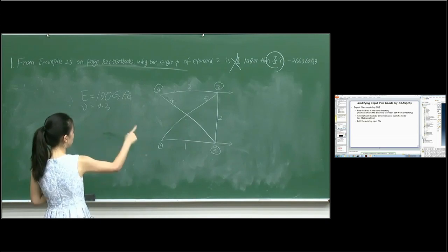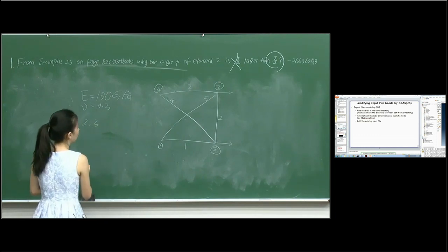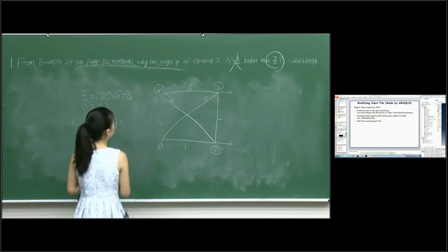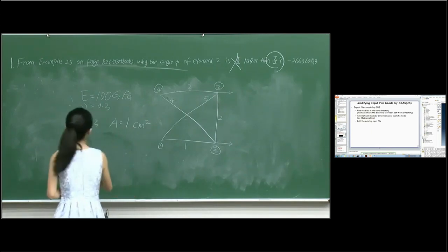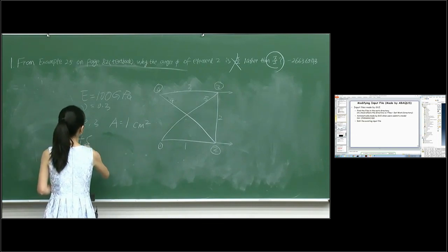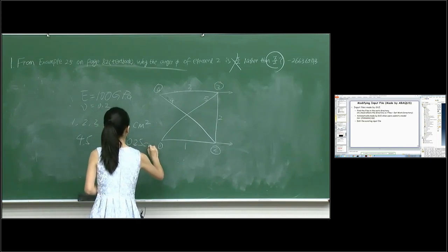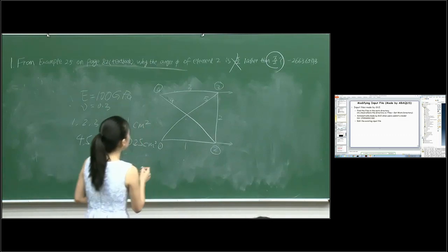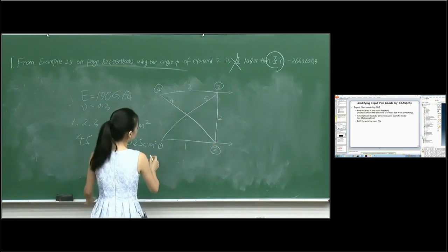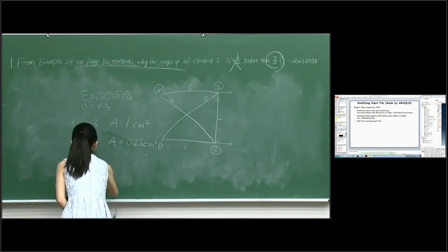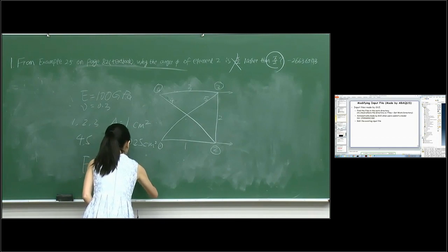So for the horizontal and the vertical trusses, they have cross-section area of 1 centimeter square. For the diagonal truss, it has a different cross-section area. And the loading condition, I simplified it, so it's at node 3 and node 2, in the x direction, 10,000 Newton.